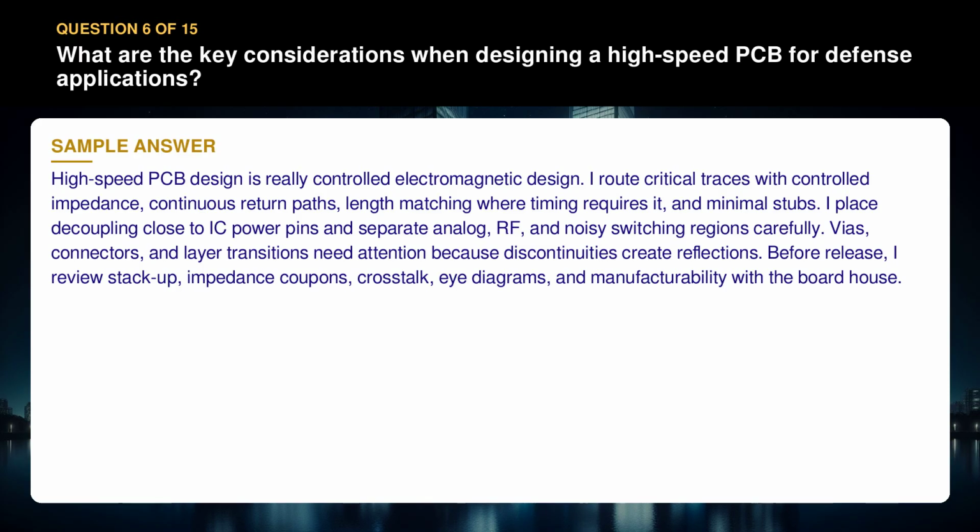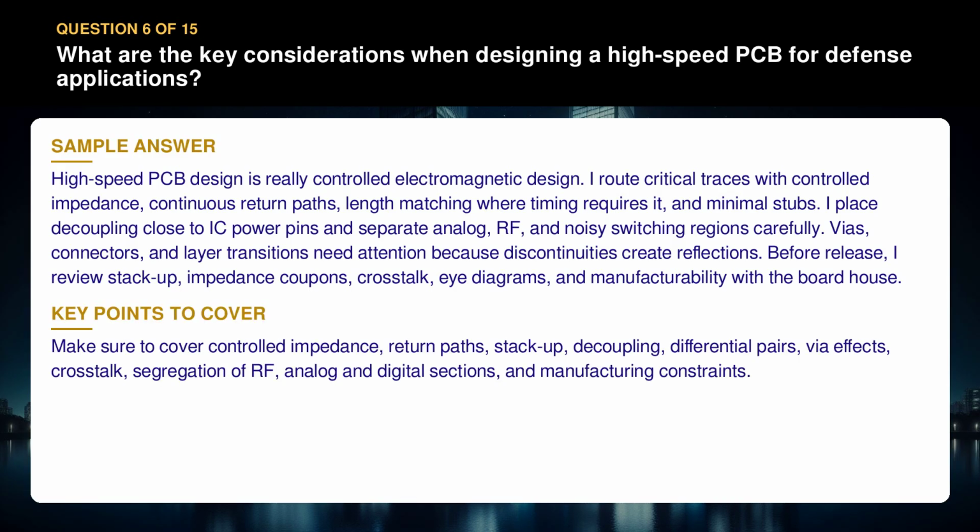Before release, I review stack-up, impedance coupons, crosstalk, eye diagrams, and manufacturability with the board house. Make sure to cover controlled impedance, return paths, stack-up, decoupling, differential pairs, via effects, crosstalk, segregation of RF, analog and digital sections, and manufacturing constraints.